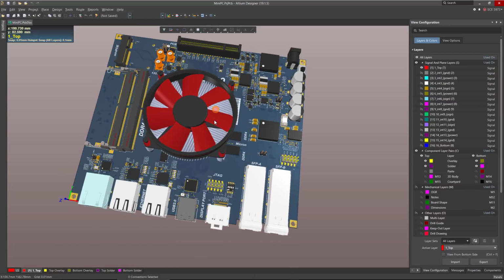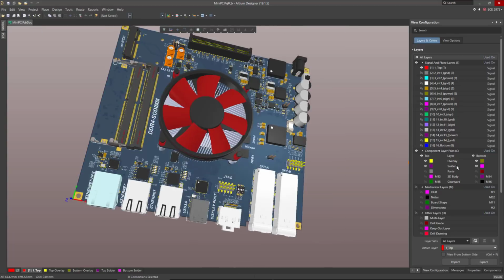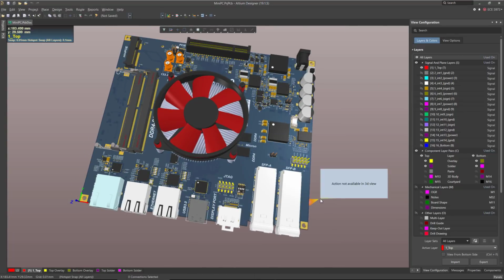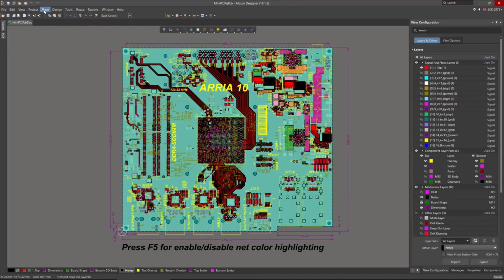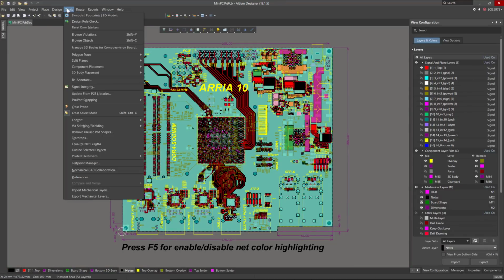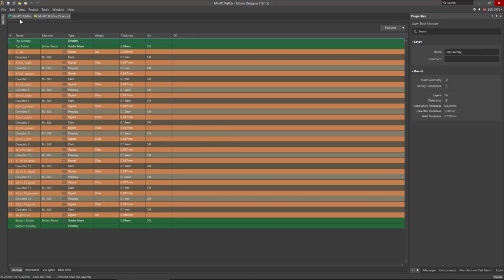If we flip the board, you can see the bottom, what is on the bottom, and this is a 16 layer PCB. Now let's also take a look at this and see if they used any micro via on the stack. So we go to the design, layer stack manager, and here you can see the FPGA chip. Let's go back, sorry.